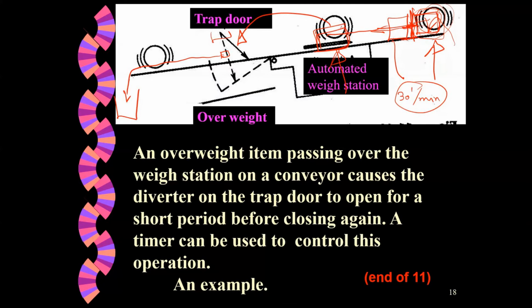The weight of the two is registered by the weigh scale. And as it goes here, the very first package that is underneath the barcode station gets a label with double the weight. And the one behind, which is clinging and attached, just leaves without a label, and the two drop here. So you have one package with double the weight, and another one with no label.